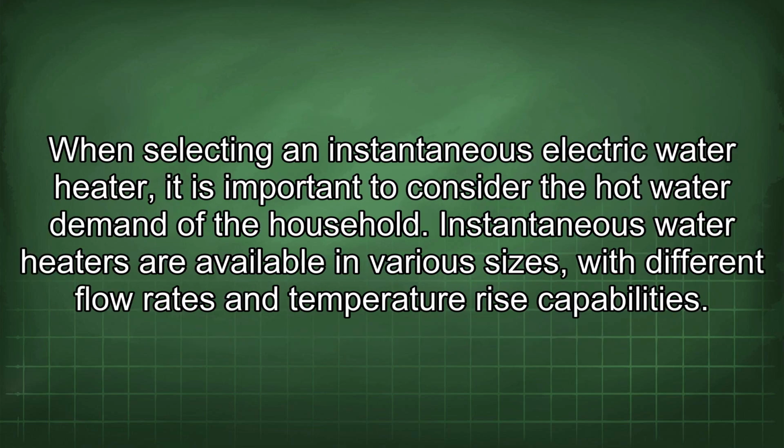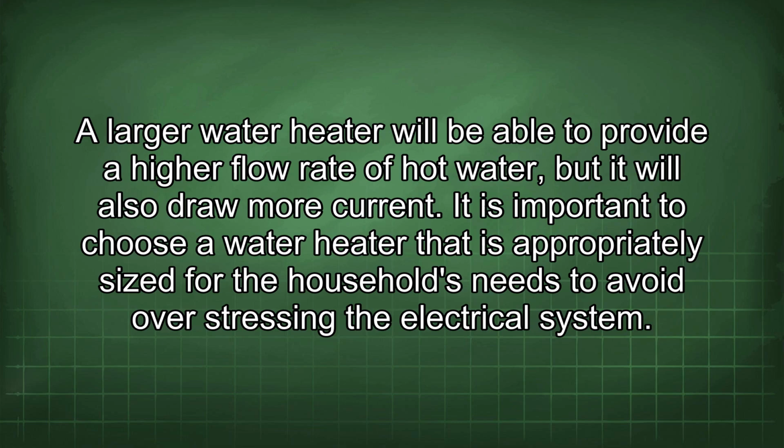When selecting an instantaneous electric water heater, it is important to consider the hot water demand of the household. Instantaneous water heaters are available in various sizes, with different flow rates and temperature rise capabilities. A larger water heater will be able to provide a higher flow rate of hot water, but it will also draw more current. It is important to choose a water heater that is appropriately sized for the household's needs to avoid overstressing the electrical system.